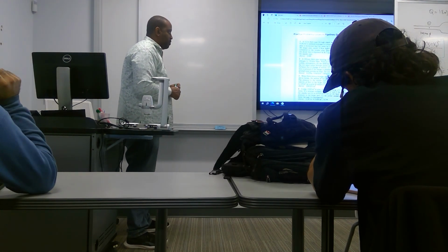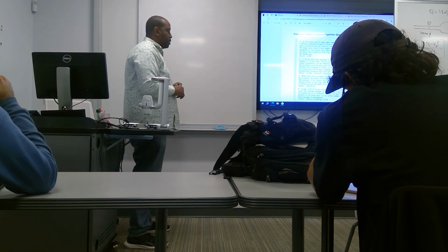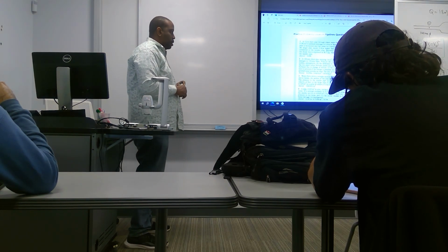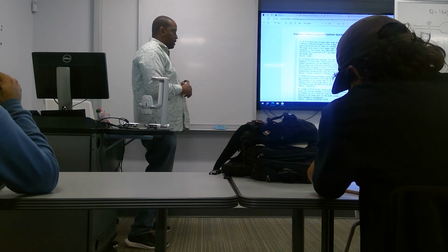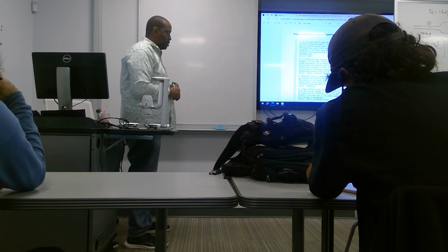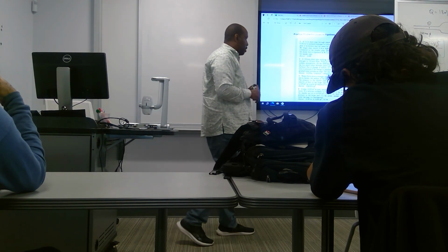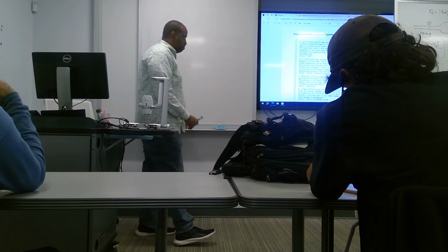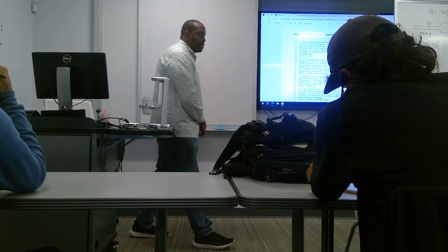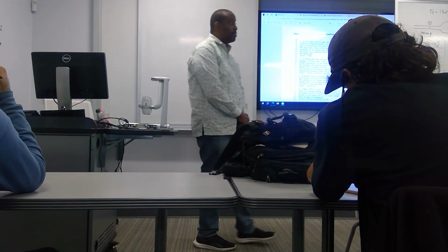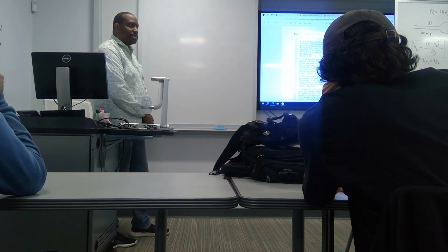It says water flows down a straight inclined pipe. At point A, 45 meters above datum, the section of the pipe suddenly doubles in area. The pressure in the smaller pipe at A is 860 kPa, and the velocity of flow in the larger pipe is 24 meters per second. Find the pressure head at point B, which is 2.5 meters above datum. The trick in this question is how you draw it, because if you don't draw it right, you're not going to get the right answer. So how should we sketch this?